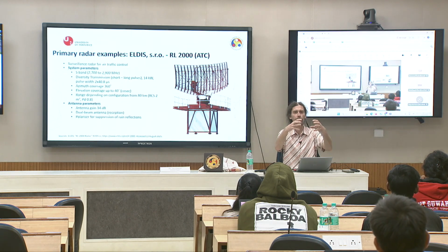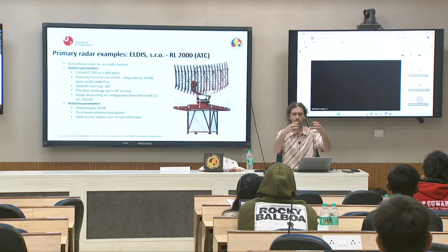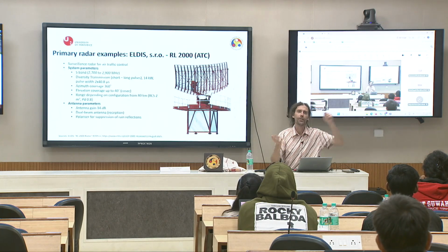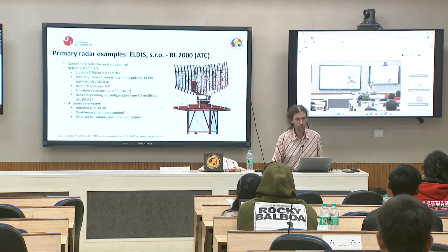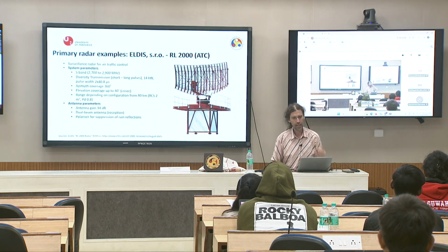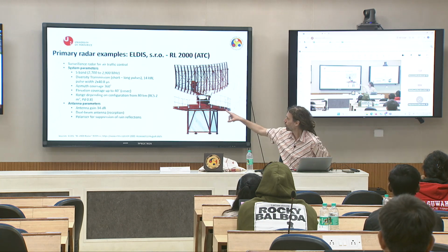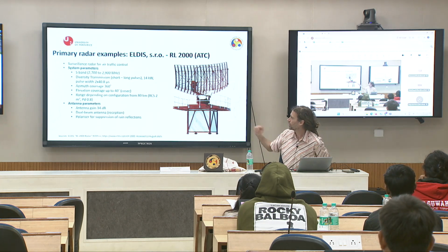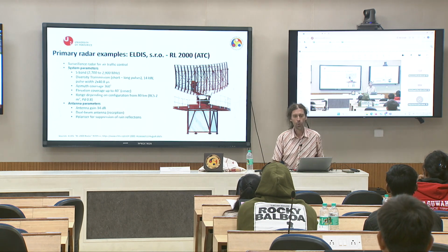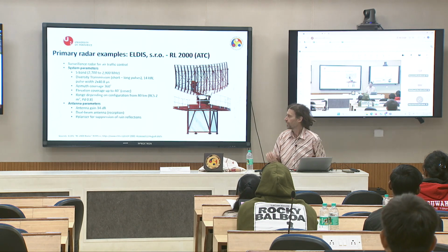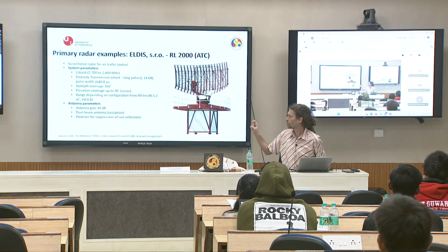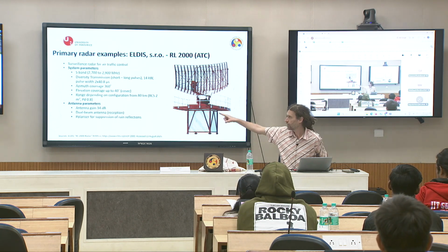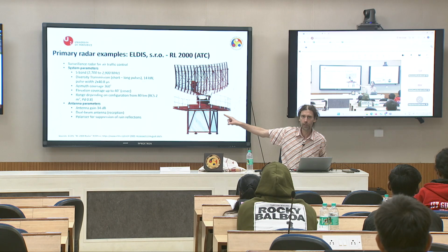But a small UAV, I doubt that you will see this small UAV from 80 kilometers. So range depends on configuration, and usually you see more parameters there. So this information says that I can detect a target up to 80 kilometers that has a radar cross section of 2 square meters with a probability, and be careful, there is also a probability of 80%.